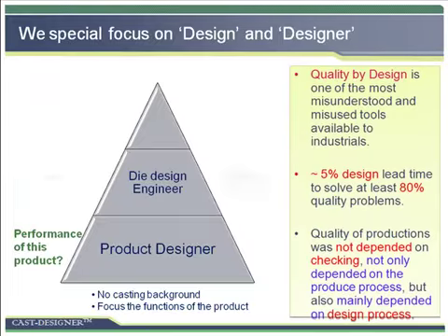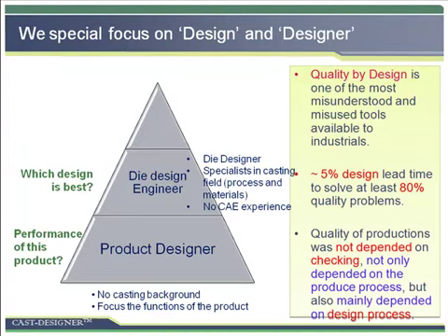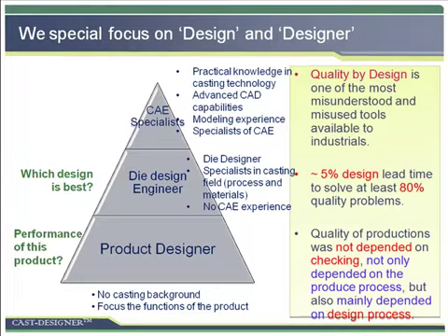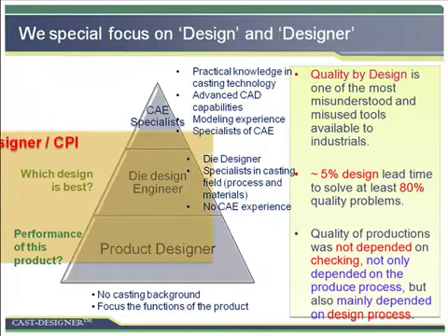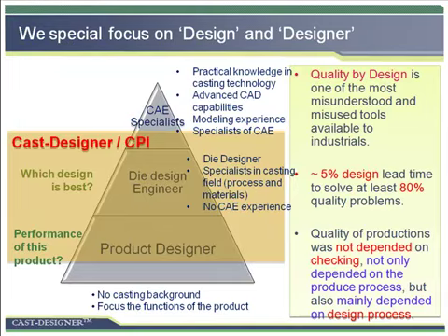We also serve the die design engineer to help them select the best solution for manufacturing, such as defining the casting solution, designing the casting system and optimizing it, and validating the casting system in a simple and express way. Moreover, our solution also provides a deeper and more detailed study of the whole casting process for CAE specialists. With Cast Designer, it is possible to optimize a casting design by detecting the part features with potential metal flow and solidification problems, and evaluating riser and chill, gate system, and pouring system design alternatives in the early design stage.